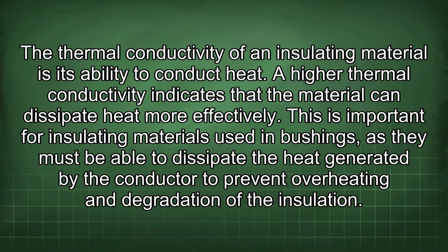The thermal conductivity of an insulating material is its ability to conduct heat. A higher thermal conductivity indicates that the material can dissipate heat more effectively. This is important for insulating materials used in bushings, as they must be able to dissipate the heat generated by the conductor to prevent overheating and degradation of the insulation.